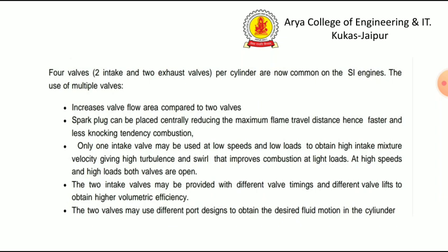Multiple valves. Four valves per cylinder are now common on SI engines. The use of multiple valves increases valve flow area compared to two valves. Spark can be placed centrally, reducing the maximum flame travel distance and hence giving faster combustion with less knocking tendency.